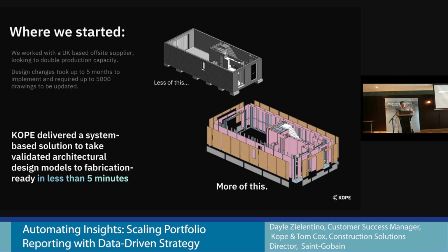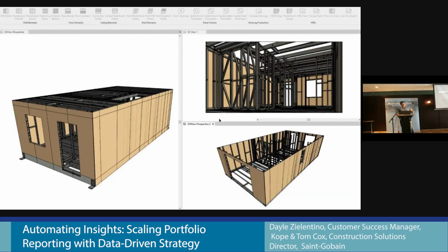So what the team did was take that BIM, that holistic walls, floors, systems as a logic, and actually get it down to their individual parts so they could go through the manufacturing floor. Little video here. What you can see is, tool by tool by tool, working through one system, one product at a time, starting with that core metal chassis, working through and applying boarding, plasterboards, having to know exactly where all the screw runs were going, the nail fixings, the lot. And the team would basically go through with that manufacturer and work out system by system, understanding the wastage, trying to optimize those boards and pieces, and running through that process.